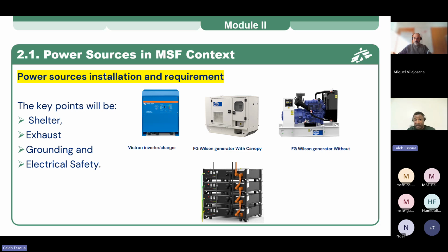Some inverters nowadays can be waterproof, but it's good to check the specification of this. If you have to put it inside or you can put it outside without any problem, you have to verify the specification. But basically for this Victron inverter, it's good to put them inside and ground them properly. And when you are doing your installation, you have to make sure that everything is all right before you leave the site. Otherwise, you will start getting problems with these things.